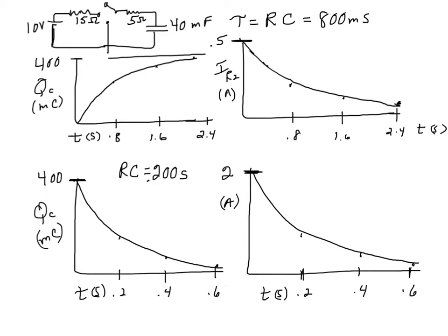So I rewrote the circuit here just so we didn't have to flip back to the other page. The voltages, the resistances, and the capacitance. Now to make the plots, we need to know the time constant. For the circuit where the switch is closed here, with both resistors, current will flow from the battery through 2 resistors onto the capacitor and from the capacitor back through the battery.